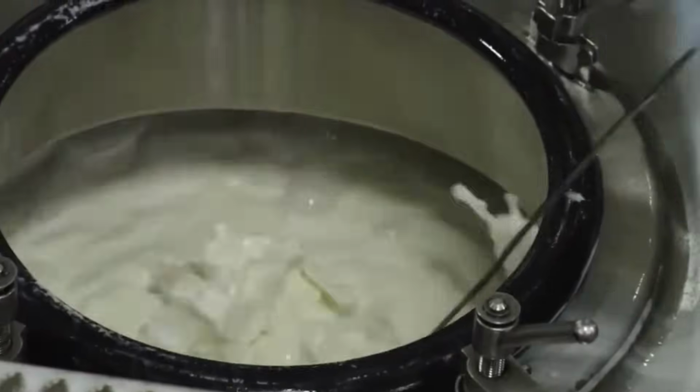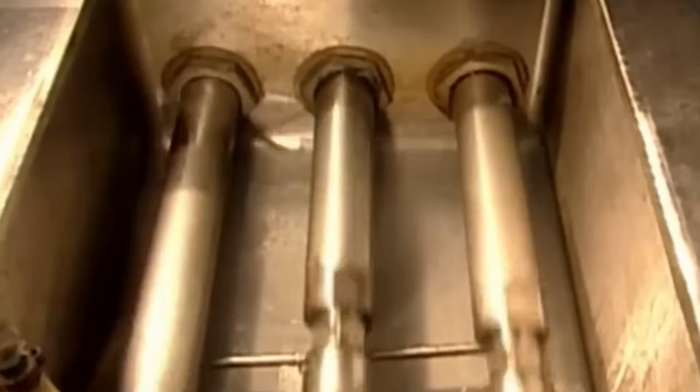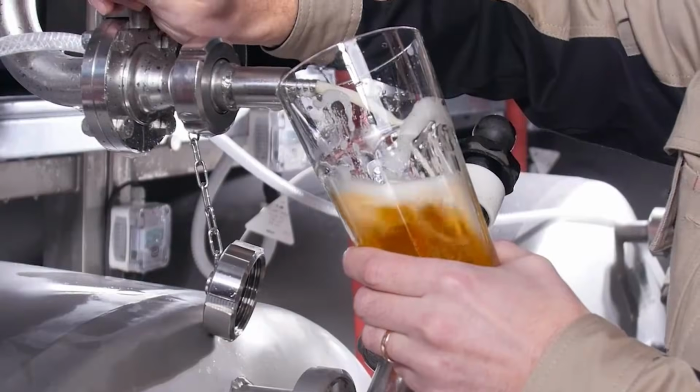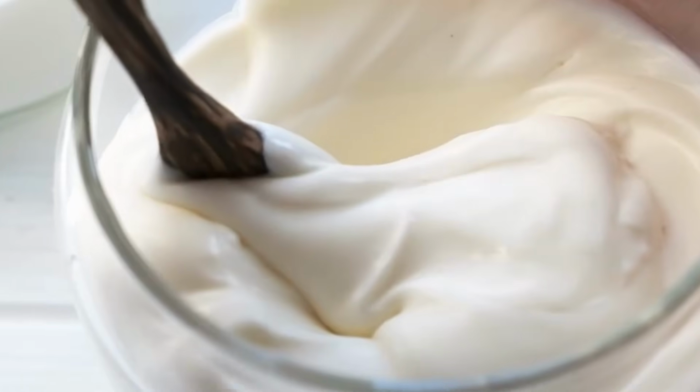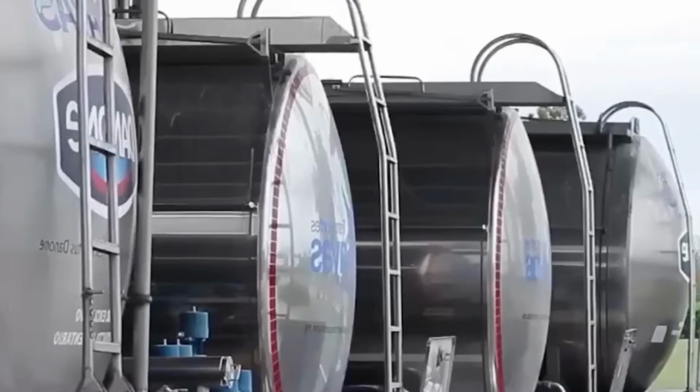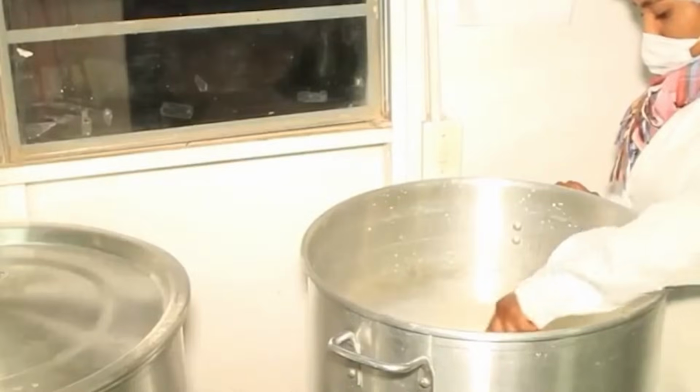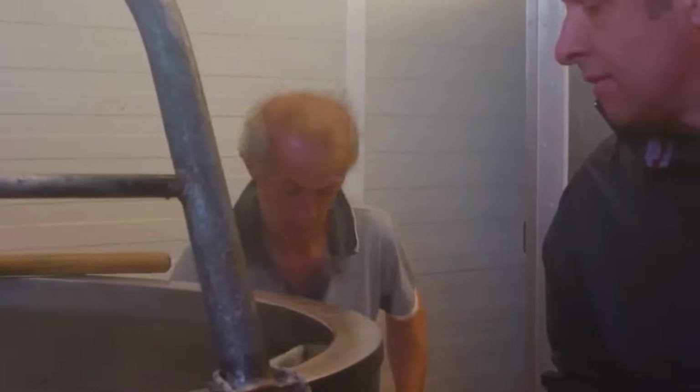Products requiring enrobing are transferred to chocolate coating stations. Bars move on a mesh belt through a curtain of tempered chocolate or compound coating held at 32 to 34 degrees Celsius. Excess coating is removed using air knives, and toppings such as crushed nuts or cookie bits are sprinkled over the wet coating before it hardens in a subsequent cooling tunnel maintained at -15 degrees Celsius.